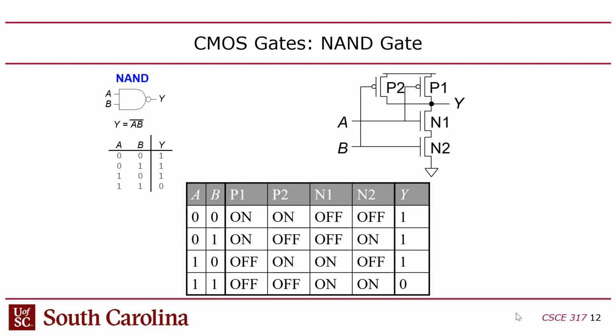You have to have at least one input 0 to pull up, and you have to have at least one input be 1 to pull down, right? Well, if you think about an AND gate, the AND gate is only true if both inputs are 1, right? Well, if that's the case, that's impossible, right?